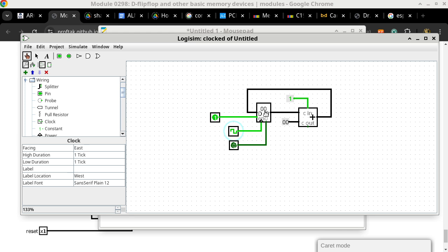It does not. Okay, so if you want that to be recorded or at least reflected so that you can see it, you need an output pin connected to C out. In this case, C out corresponds to K8 in our nomenclature, because K8 is the hanging carry bit that does not match any of the other bits. That's the overall carry in this case.